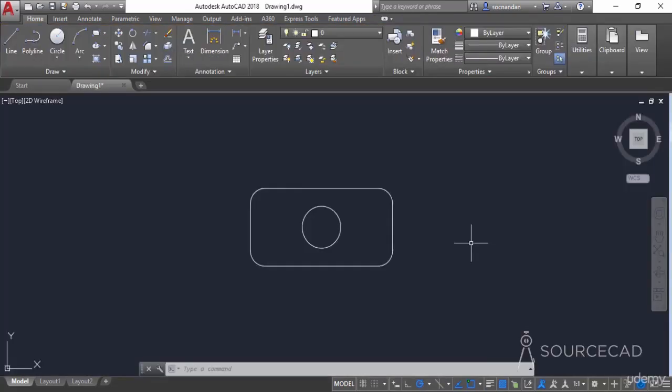So we'll create the dynamic block, but with the help of geometrical and dimensional constraints. I've made this drawing here, and it's a simple rectangle and a circle. The rectangle has been filleted at all of these 4 edges, and now we'll convert it into a dynamic block.